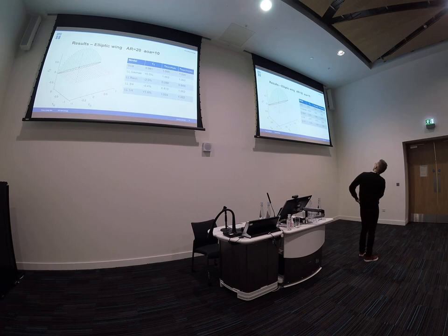But this is using the drag that you look at when you look at what are the forces that I evaluate on my blade. And this is the Oswald efficiency when I use a drag I get from a far field analysis. And the catch here is that the far field analysis you can only do when you have a steady uniform inflow case, which is never the case for a kite. So this is something that you can use for straight line conditions. This is very close to 1 for all of them, so that's happy.